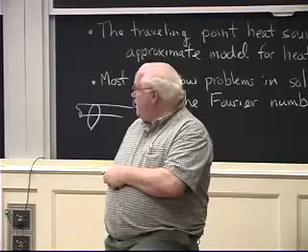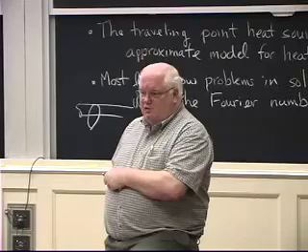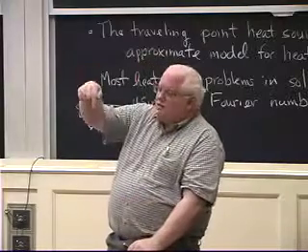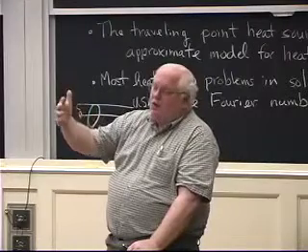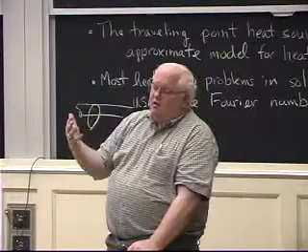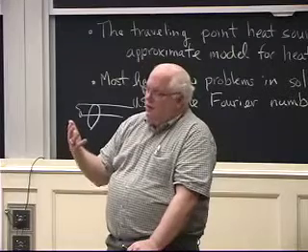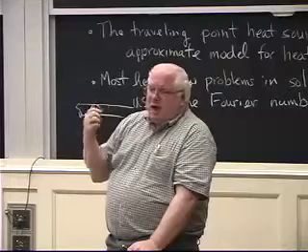And the reason for that is helium has the highest ionization potential of any gas, 24 electron volts. As the laser comes in and heats the surface and vaporizes metal off the surface, you generate very high temperatures, so high that you actually can ionize the air.